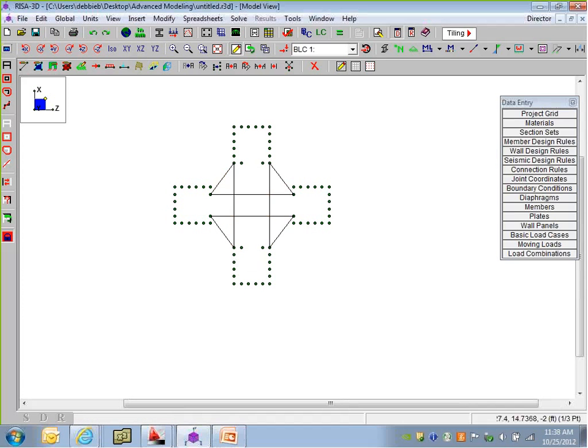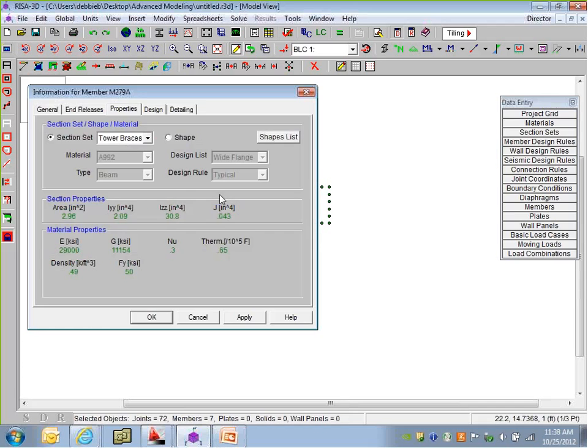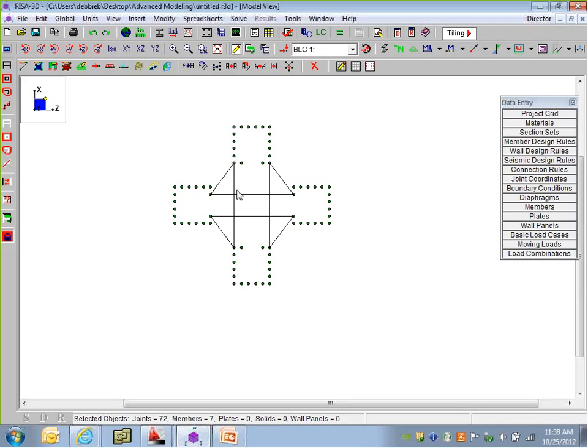If you don't model merge, that means that the loads that happen along this beam and the beam that crosses it will not get connected. So if you just see a member across there that does not have a joint at it, and you don't model merge this area, then these will just act independently. If we do model merge it, it will get a joint there, and then those will actually interact.